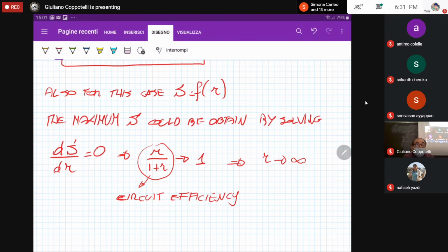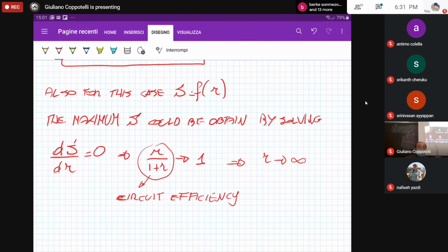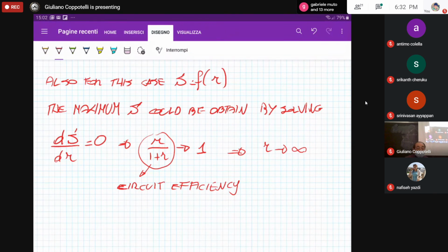So pay attention, because if you would like to have your Wheatstone bridge measuring circuit operating at the maximum sensitivity with just one leg and with the maximum dissipated power available, then you also have to take care about the fact that R should go to infinity, and there should be some issues related to the differential of potential between the resistances, because R is going to have infinite value. So R2 or R1 should be infinite. So one resistance is much larger than the other one. So care should be taken.